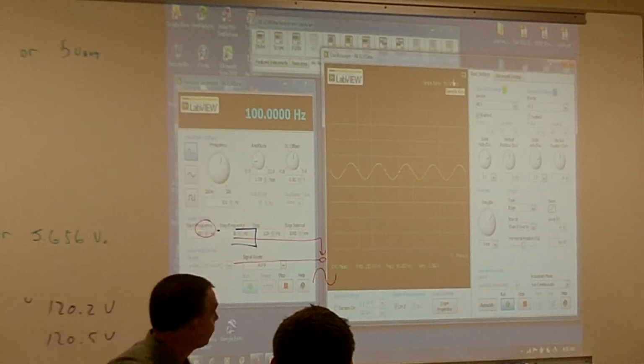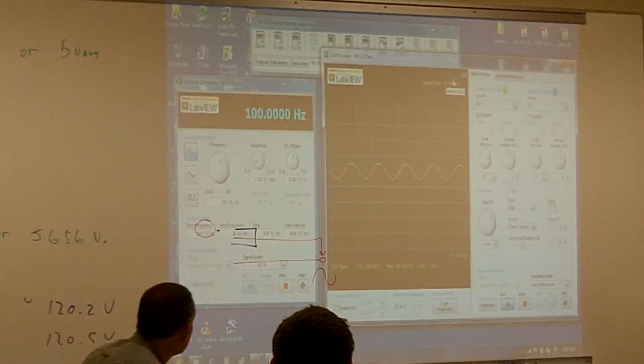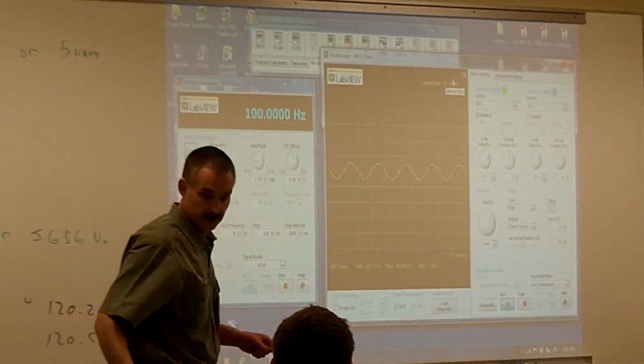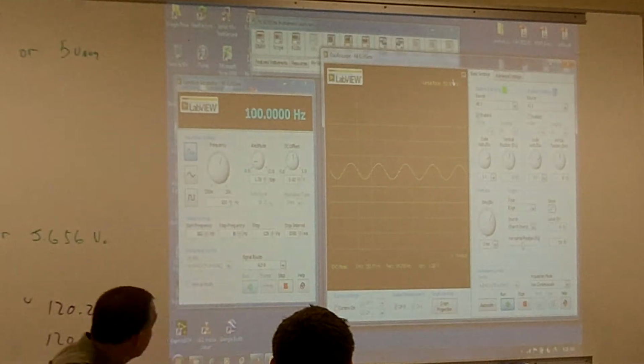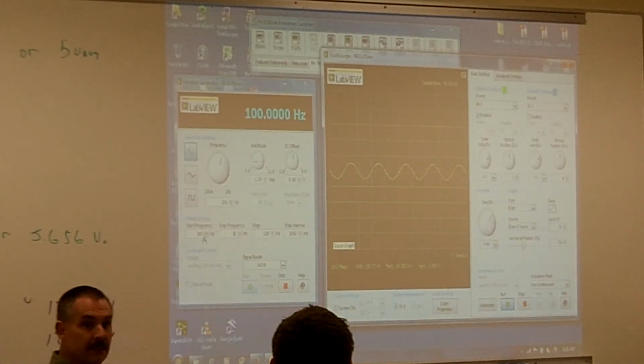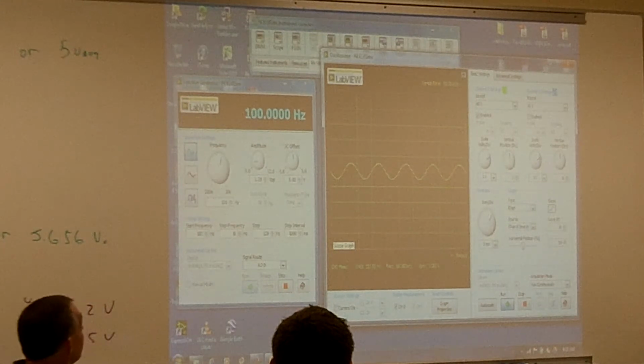Can you try one for me quick? Yep. Use a square wave at a frequency of 1.5 hertz. Okay. Put your DC offset at +5. Perfect. All right. And then just kind of mess with the amplitude, because I got my digital circuit to work by going all the way up on the amplitude. That's the only way that I counted correctly.